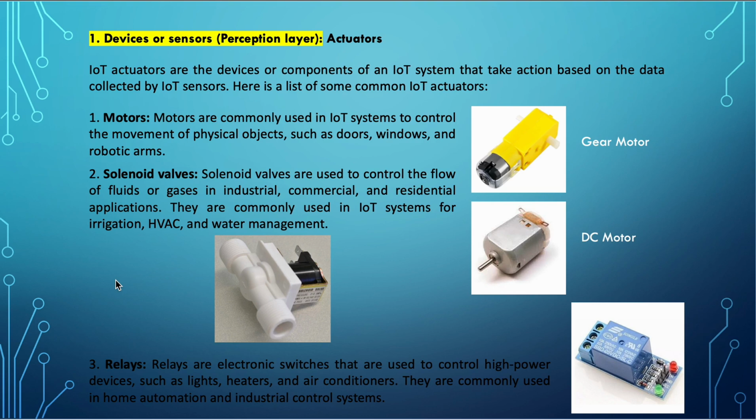If we are to control the water through solenoid valves for a paddy field, the properties of the solenoid valve should be able to handle large quantities of water. When the quantity of water becomes large, the pressure becomes large, so the machinery itself should be able to handle that amount of water. So then again, like motors, we have to check the properties of the solenoid valve for our application. When applying, we have to select the correct one.